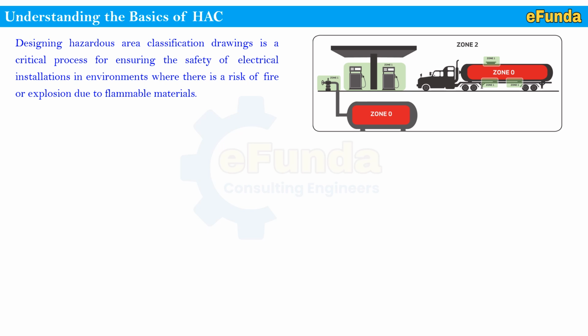The source from which the valve is getting opened, or the digital meter or pump station from which the nozzle is used to transfer the fuel into the car or respective vehicles, is classified under zone 1, and the outside atmosphere of this petrol pump facility is considered as zone 2.